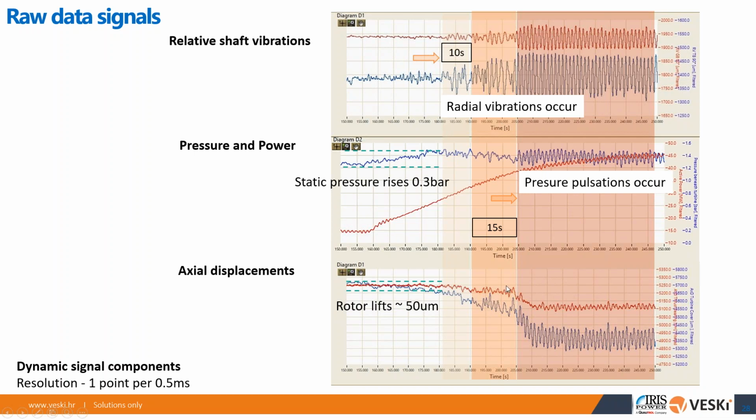You can actually see them develop on the low frequency. And then from this point on, everything is simultaneously moving on the low frequency. So this is the phenomenon. Before we got this on the first power plant, we thought, and that was a common thought, that pressure pulsations develop below the turbine, and then they cause the vibrations. But we have maybe 5 or 6 machines which we equipped with the configuration I showed you, and they all show pretty much the same behavior, right?